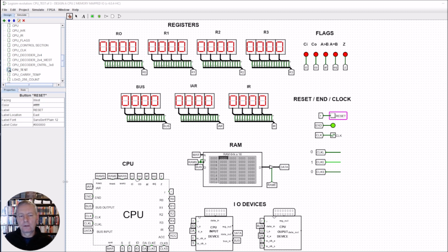As it stands at the moment, we have generated an extra set of commands, that is an extra set of instructions, which are the data in and out, and also the address in and out. Now, we can do it in a simpler manner than that. We can do it by not having any extra instructions. That is, we can use the instruction code that we already have, which in this instance would be the load and store. So we can get data in and out of the CPU using the load and store commands.